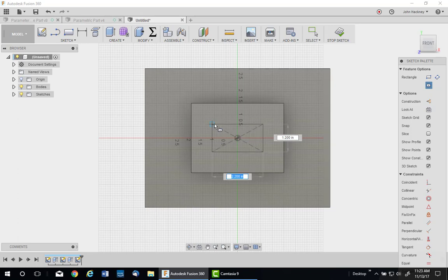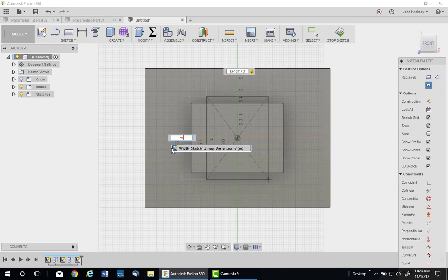So now all I have to do is type the letter and it comes up. And by the way, it's any letter. A D will bring it up in width. But of course I want a T for length, and those all 3 came up. So again, I pick it and divide by 3. Again, keep your cursor very steady until you hit the tab to lock it. Now I pick the other one. I want to type W for width, select it, and divide by 3. Again, lock it or it'll disappear.